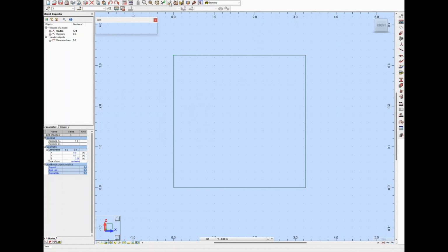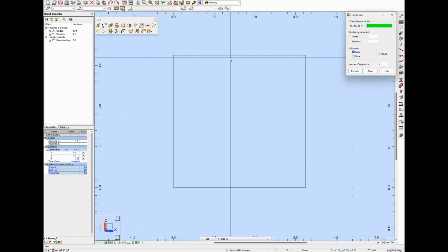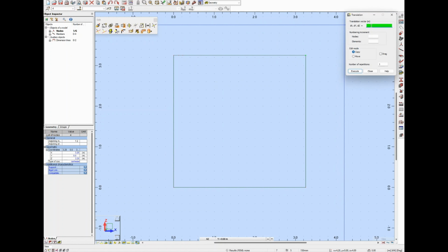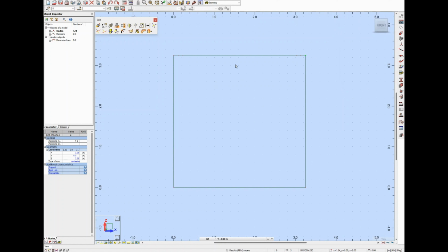So all I'm going to do here then is just pop some nodes. I'm going to move around some nodes from the points into where we would have our chamfer, which would be 125 mil. So the wall thickness is 125 mil, and then the chamfer is 100 mil, so 100 by 100. So 225 would be the distance for the node, and that's where we're going to take the max hogging in the roof of the culvert and also in the outside of the walls. You can add as many nodes as you want, guys, but we're looking for the results, and to get the values and the results we would need to set up nodes.